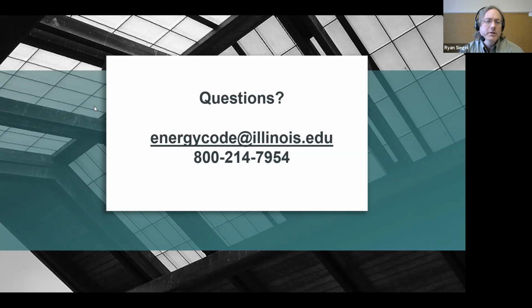Then, the 750 CFM threshold that you mentioned, Sean, question regarding, does it apply to each individual classroom unit ventilator or all the unit ventilators combined? And checking, it looks like the 750 CFM is for multi-zone systems. So individual unit ventilators would not have that minimum threshold. So the DCV would apply for individual unit ventilators.